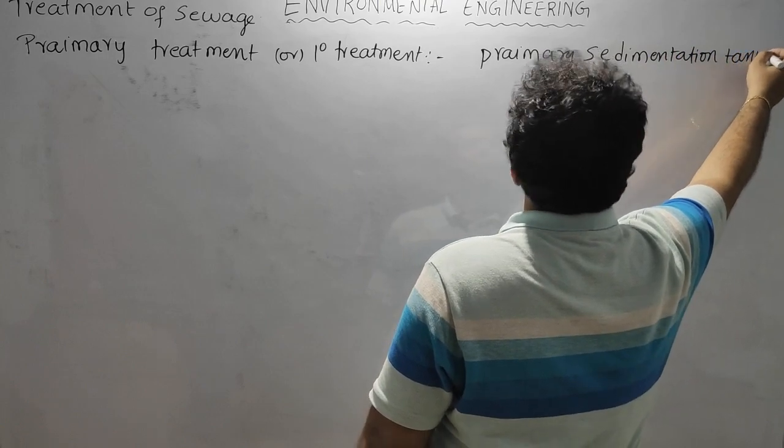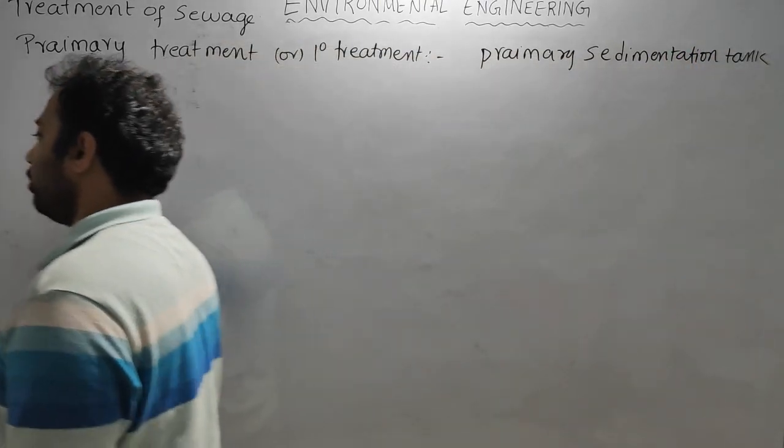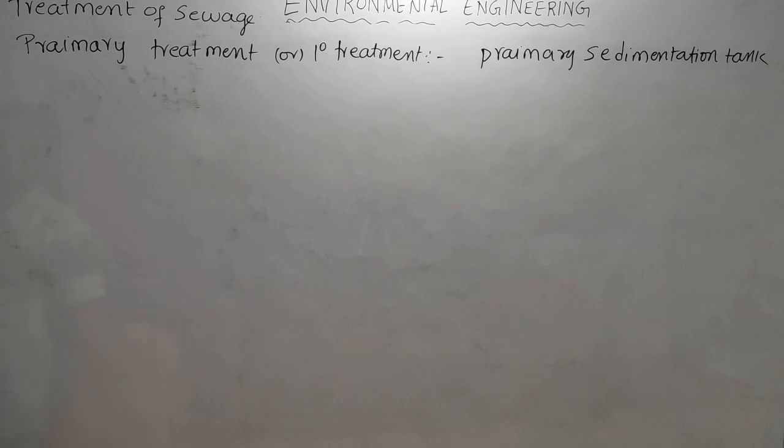So here, primary sedimentation tank, if we go back to water supply engineering, we call this primary sedimentation tank also a type 1 settling tank. Why do we call it a type 1 settling tank? Because the particles which settle there settle like a discrete settling.